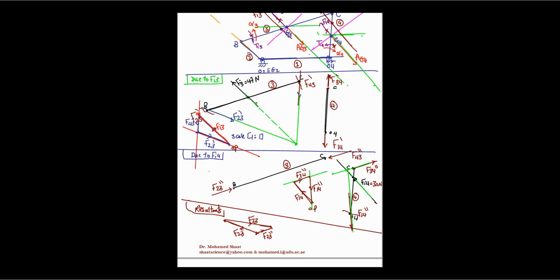So we got one reaction force, one resultant one. We still have two, the F14 and the F34 or F43. It doesn't matter, because F34 or F43 both are equal with the same magnitude but in opposite directions. So let us work over the F43. The F43 dash, we got its direction. This is its direction. It goes down, right? And we got its value from the analysis of the first case. We got it as 20 Newton. Make sense?